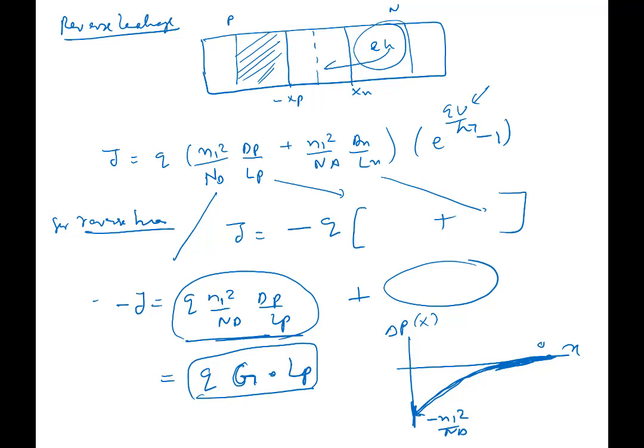So carriers are getting generated on the P side, and electrons and holes, in this case, the electrons move in this direction. What is missing is that there is generation inside the depletion region also. If you want the story to be complete, you have to take into account generation within the depletion region. If I look at generation inside the depletion region, if you recall, R equal to Pn minus Ni square into 1 over tau, Pn plus n plus 2Ni, right? This is our simplified expression. And we are talking about reverse bias.